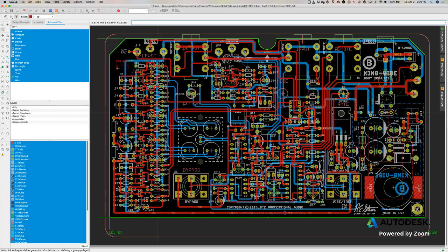First thing I like to advise is, even though it's obvious here that I have it activated, make sure that you have the settings to auto detect board outline. The screen line that you see right here is on a layer called the dimension layer. And that layer is the guidelines which are going to confine where your circuit board is going to be, where all your parts and your routing should be located.